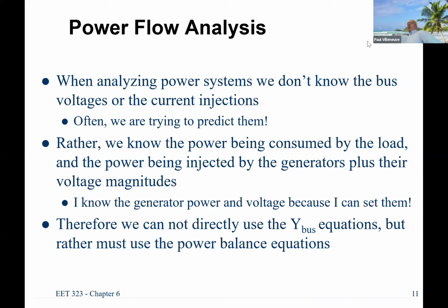So we can't use the Y bus, the V equals Y bus inverse times I, to solve for that. We have to figure out a way of writing equations to actually allow us to solve for the voltages. And since the systems are nonlinear in nature, we have sines and cosines, right? We have complex numbers there. We have to use the Newton-Raphson algorithm to go ahead and solve that.